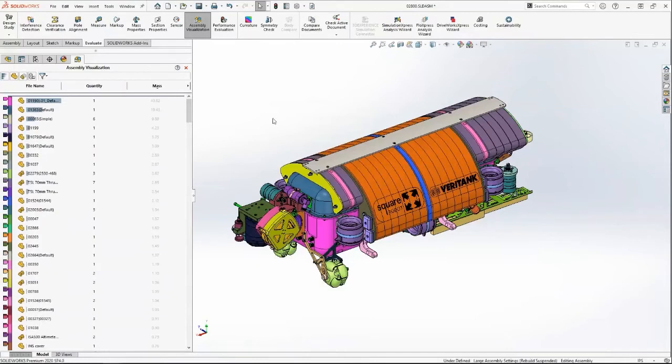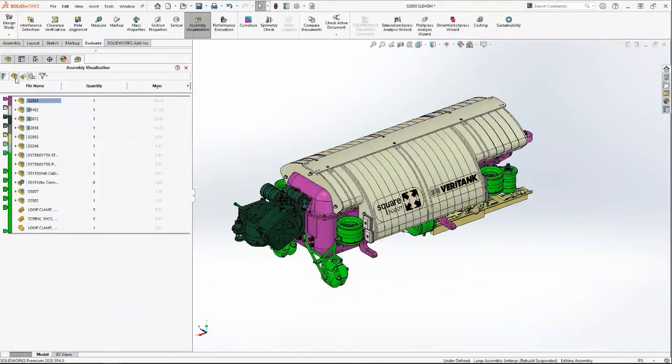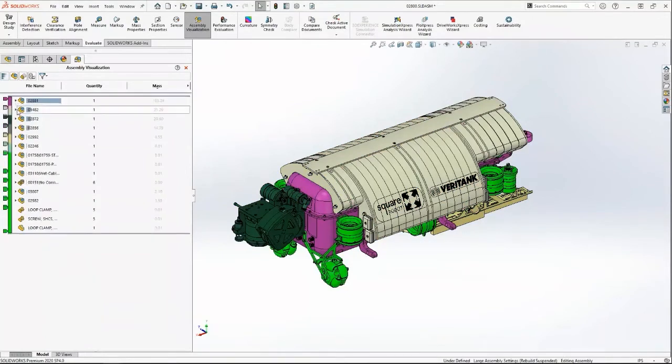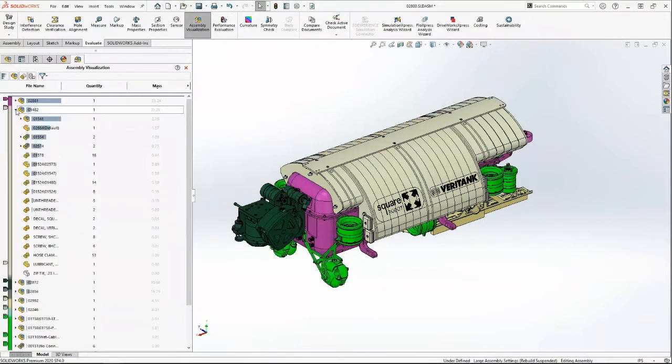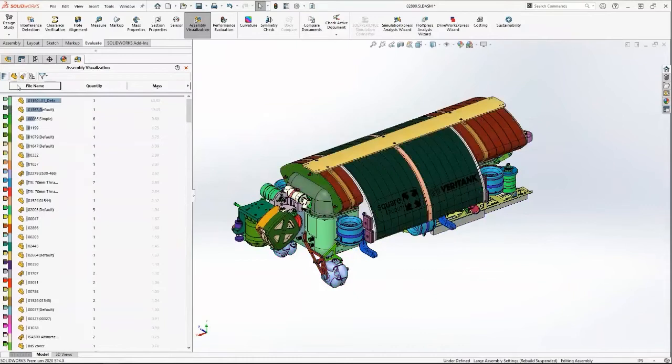I mentioned there was a little tool that we have available that's inside assembly visualization. Actually, before we talk about that, there is our flat and nested view. If you're familiar with this, this is going to be a different way to, again, visualize your top level. So all of your sub-assemblies are nested under, obviously, its sub-assemblies. This is giving us our top level view, right? You can obviously set it to be flat, where we see all the individual parts.